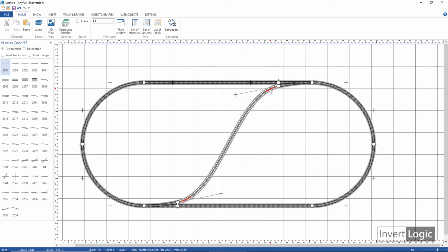You see these two rail lines. These two rail lines tell us that this curve is a little bit very sharp and you may have a derailment here, so you have to figure out how tight you want your tracks to go. But I would say that you always have to check how tight your locomotive can handle the tracks, how tight your rolling stock is going to handle the tracks, and then you have to decide. So this is just to show you the basic functionality of how you can bring in the tracks, how you can join them, how you can use the turnouts and do basic things with the tracks.